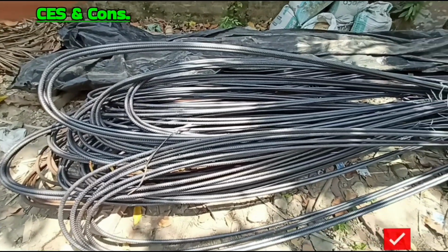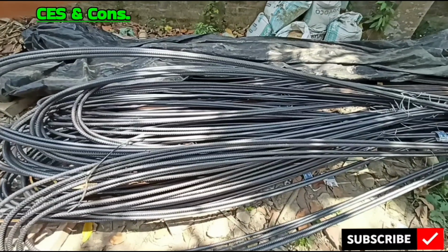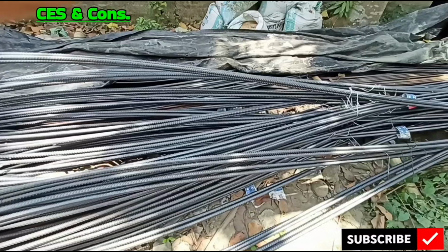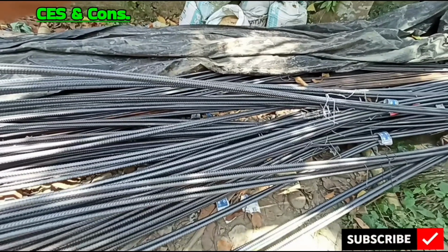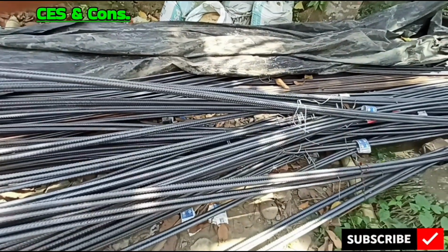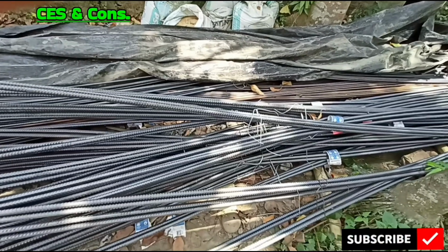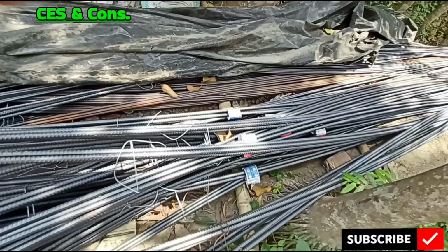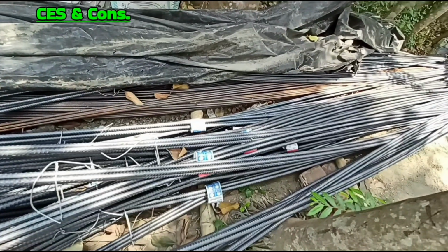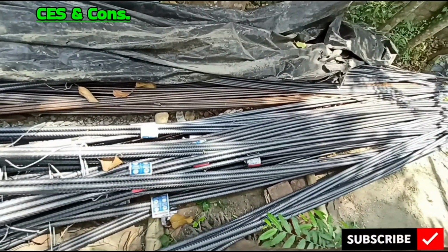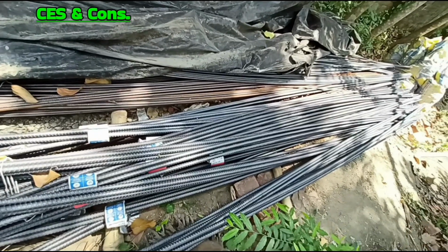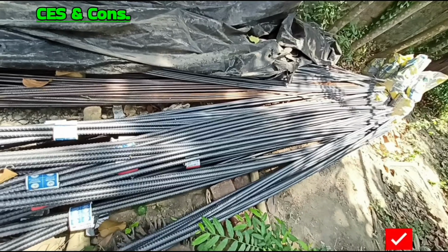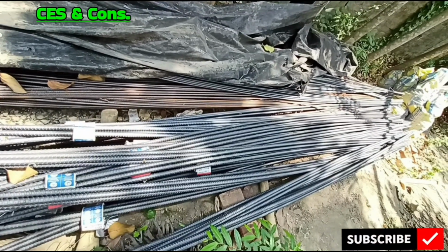As per IS 456-2000, clause number 26.4, the minimum concrete cover in this beam should be 25 mm. For severe environmental exposure, increase this cover by 10 mm. While using, the bars should be free from visible defects, rust, loose scale, oil or grease. For this plinth beam, the minimum tensile steel should be 0.85 bd divided by fy, and minimum compression steel should be 0.25% of cross-sectional area of the beam.